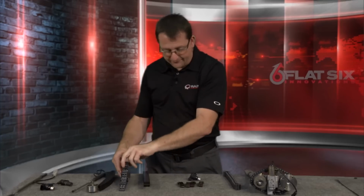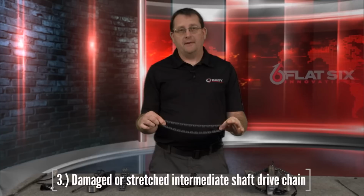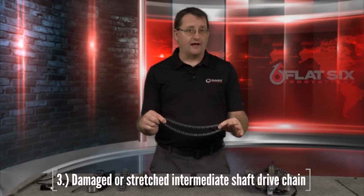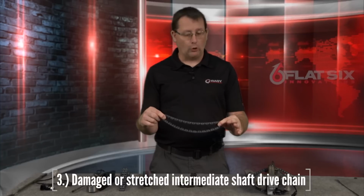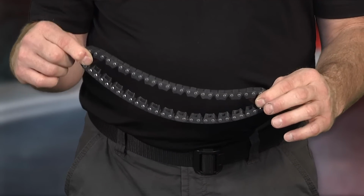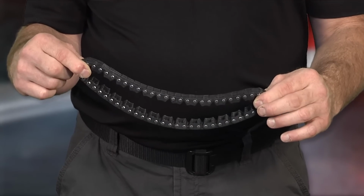Then we have the drive chain for the intermediate shaft. This one is an inverted tooth. It can also be a duplex style on the 5-chain engine, since that would be an early one. This chain, if it starts to stretch or wear a little bit, or if its wear pads start to go bad, it will also give you a little bit of deviation.